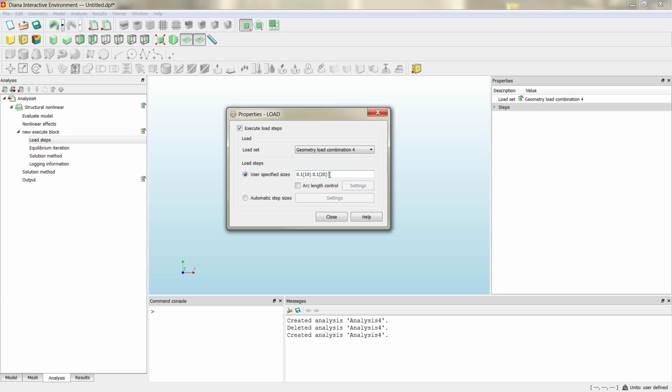And then also you can remove part of the load. Now if we want to bring back our structure to the one-time loading, we can just remove 20 steps of load, or even 25, and we will get then just half time the defined load.